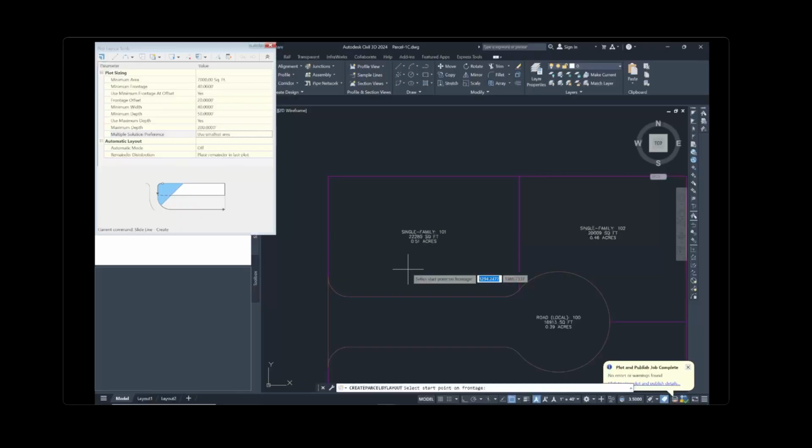We can specify the start and end point of the parcel frontage as shown in the following image. This is the starting point. When you move the cursor to specify the end point, a line displays the proposed frontage, as we can see here. We're going to find the intersection there. End point. Good. When you're specifying the frontage starting point, do not snap to the beginning of the curve. If the frontage starts at the beginning point of the curve, no solution will be found.